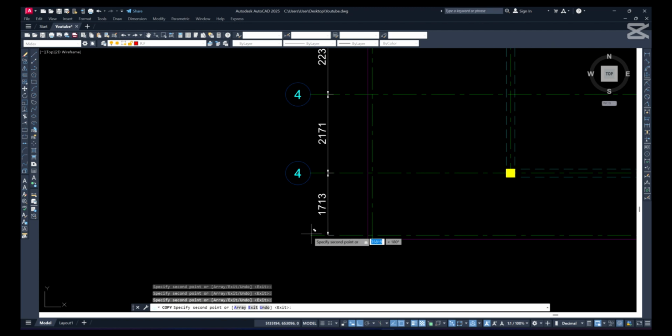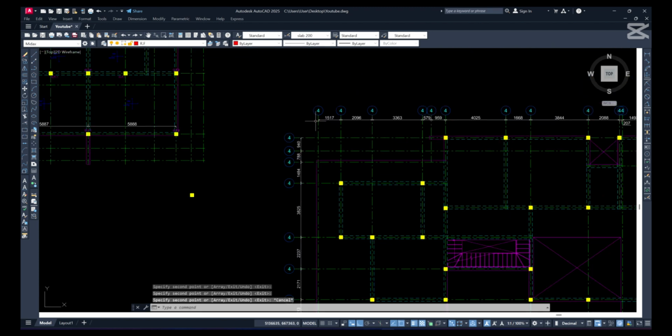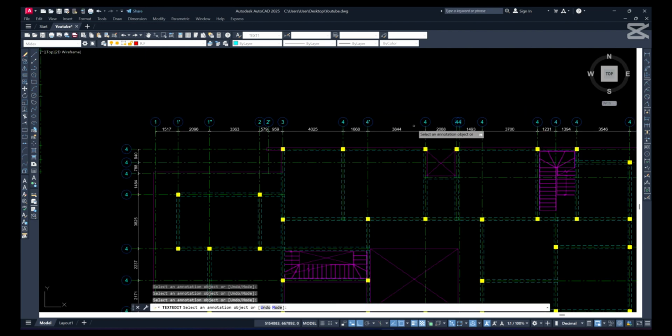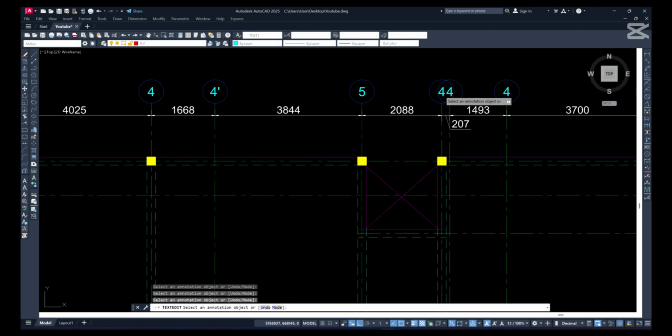Mind you, if the y-axis is numerical, the x-axis is always alphabetical, or sometimes the architect will provide you with grid lines to use. So where you don't have a grid line showing, you can use maybe the grid line before that grid line. Maybe if it's the grid line before, that grid line is 3. So where you have a new grid line that's not from the architectural side, you can just use prime, call it prime or A, to show that grid line is different, it's new, it's not from the architectural part. But in this case, we're assuming the architect didn't give us a grid line to work with. We're just using our own grid line.